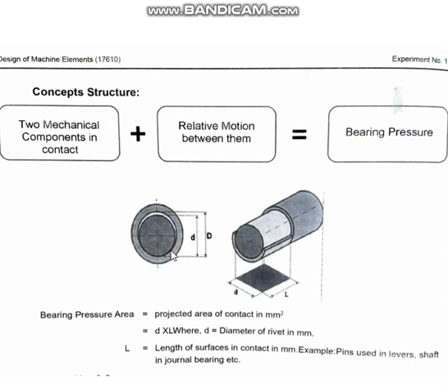Here also, what is the stress? How do you say bearing pressure? You write small p, and suffix B. That is bearing pressure. Bearing pressure is load upon area. The same formula. See, all the formulas are the same, whether it is for tensile stress, crushing stress, transverse shear stress, compressive stress, and this bearing pressure, all P by A. So here P we know, whatever is the load, the force acting there, and for the bearing pressure area also, we take the projected area.